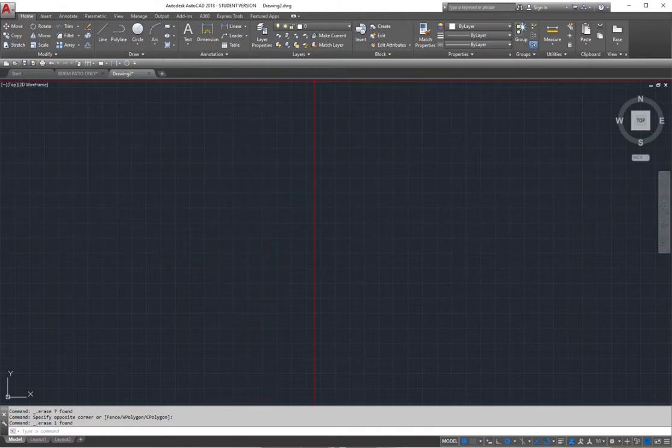So how do we do that? The first thing we're going to do is go right here. What you have been doing so far is drawing on this layer called Layer 0. This comes with any drawing that you open. Every single drawing must have a layer, and every drawing has Layer 0. That guarantees that we can draw something. Now you'll see that we can create new layers, and we can delete them if we don't want them.